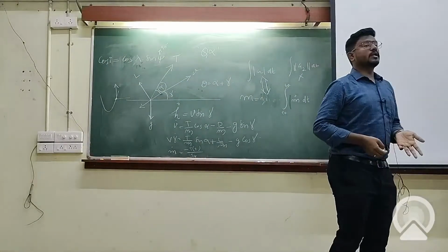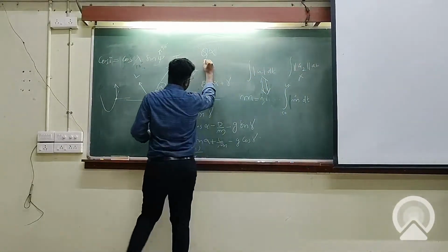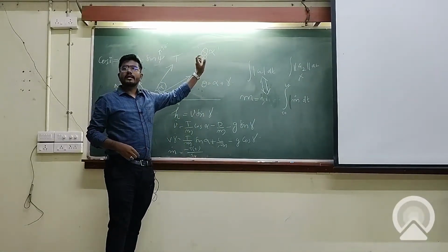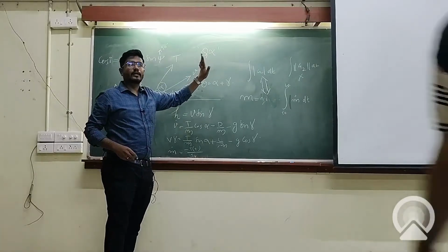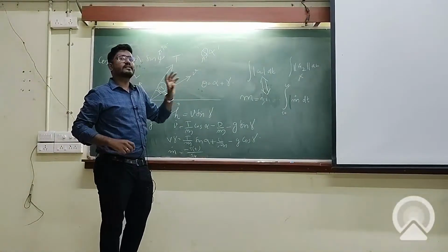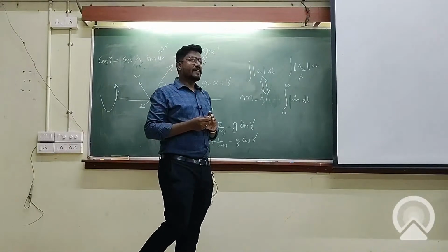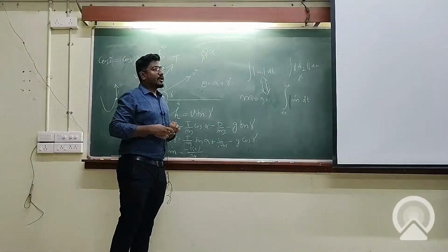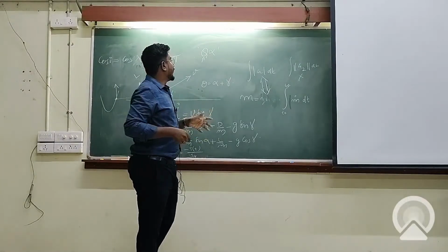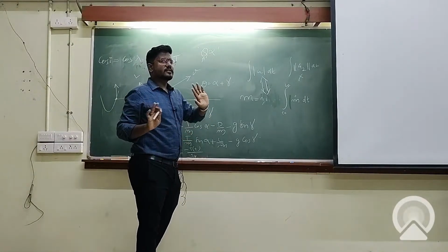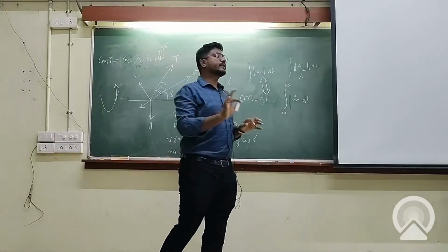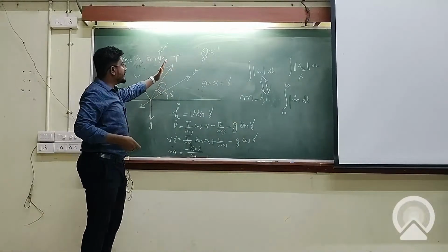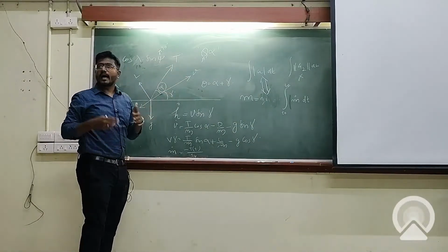But in case of non-throttleable engines, the problem is that we don't really have a handle on the dynamic pressure. Then we have to address the problem by choosing alpha. What we do there is called the gravity turn method. The term can be disputed. It's not like we are turning the gravity or anything. What we are actually doing is aligning the vehicle along the relative velocity. What does it mean? Alpha is going to 0. Your vehicle is aligned with the relative velocity. Alpha goes to 0.